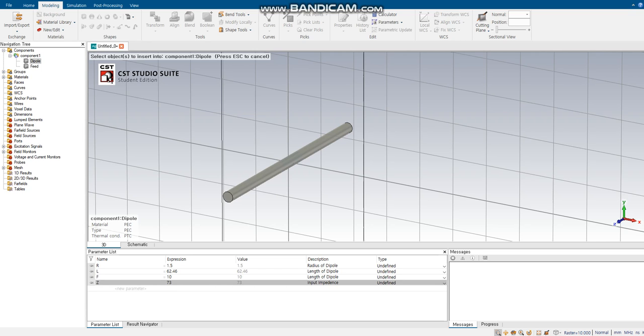Here is our objective. We will design a square patch antenna on an FR4 substrate. The frequency is 2.45 GHz and the thickness is 1.6 mm. Later on, we need to find the characteristics of the patch antenna. The dielectric constant is given as 4.7.